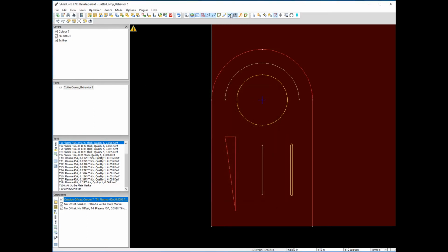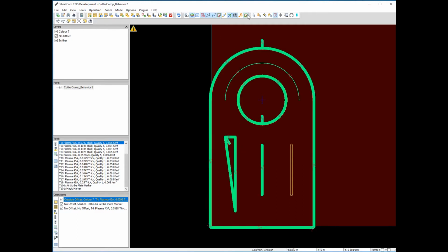Now let's see our tool path back, and you can see right here we're cutting, and we've got a lead in on the inside, and we're cutting no offset right around it. Now this distance is much shorter. That's probably what you're expecting. It's going to be half of 55 thou less here because of the curve, but that's probably what you were expecting right there. Now, if we go back to inside offset, obviously it gets short again.